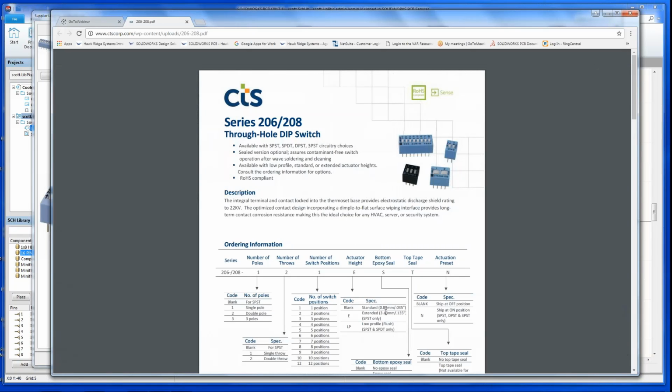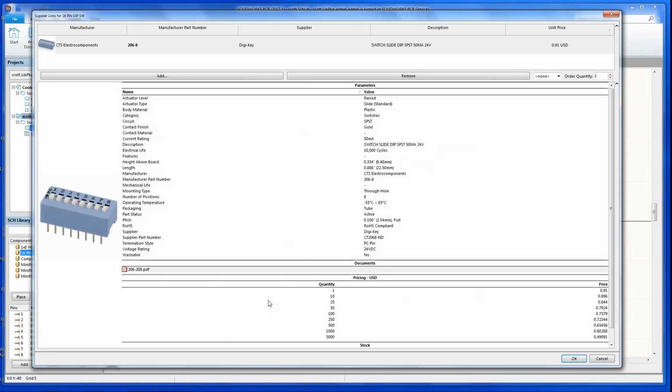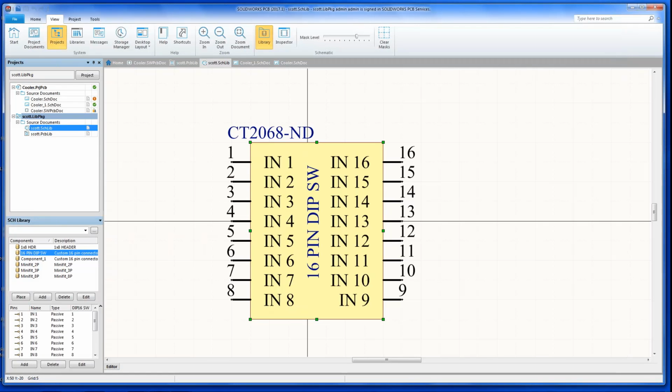And that's very handy because engineers can spend a tremendous amount of time searching for components, locating components, where in this instance, when you create a component, you can search the database that comes with the software and look at the availability of the components. If you have a database extract from your PLM system, you can create a standalone file, and SOLIDWORKS PCB can point to that file to link up with those components. You don't have to use everything that's on the intranet.